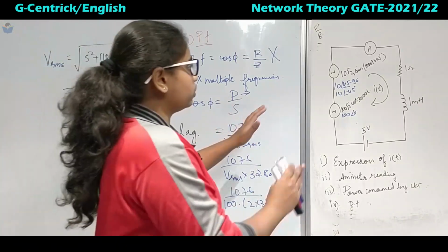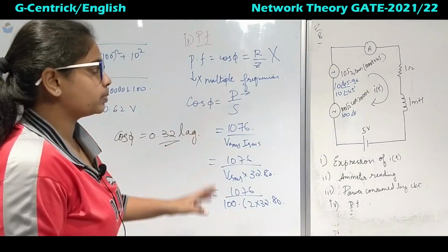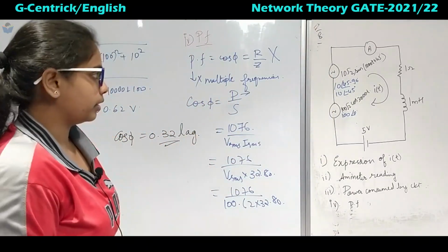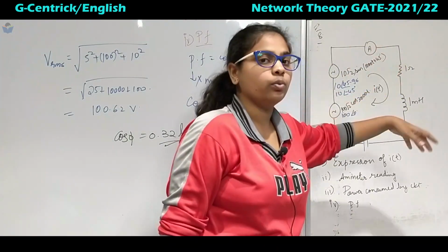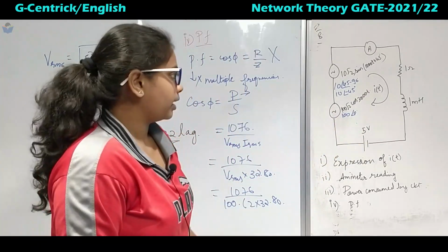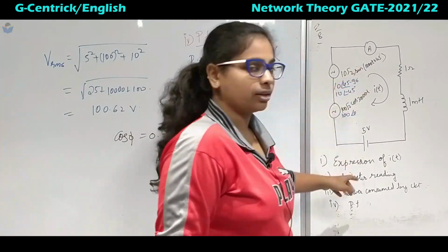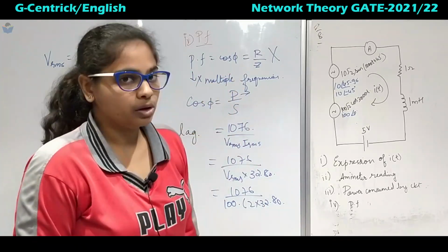In this question we have completed solving all the important concepts covering the superposition theorem. The first rule is that we have to convert the inductor or capacitor value from Henry or Farad into the ohmic value. Second, if you have different frequencies, you can solve that problem using the superposition theorem only.